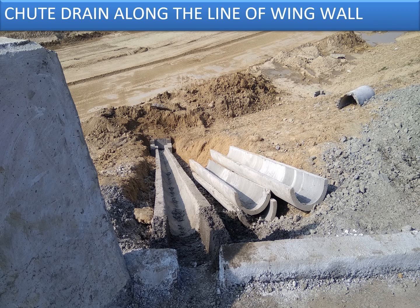So proper drainage needs to be formed so that whatever water is accumulated close to the bridge at the crash barrier locations is discharged through a proper drain, connected to the main line or the main drainage of the road on both sides. But the size of the drain needs to be decided depending upon the flow of water, and the type of pipes also needs to be decided depending upon the flow of water. Not necessarily everywhere can you have these small pipes; the drainage system has to be properly designed based on the discharge of water.